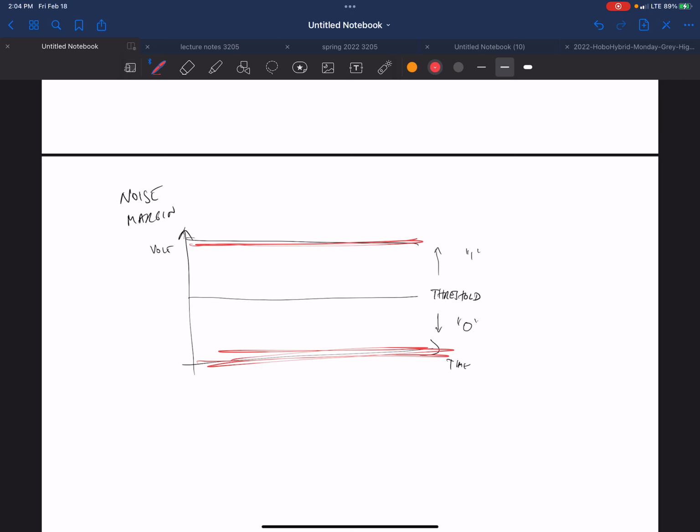But let's say you got a glitchy system or something like that. Sometimes something unfortunate happens here and there, or you get some of this thermal noise. If it gets bad enough, a 0 will turn into a 1. Remember, this is time, this is voltage. Something happens bad enough, but the further this distance is from 0 to your threshold point, from 1 to your threshold point, the more noise margin you have, the more you can filter out this unwanted noise.